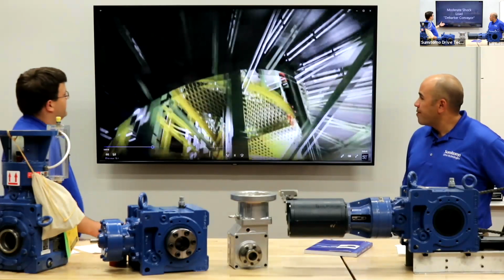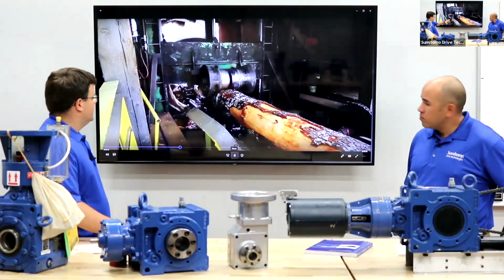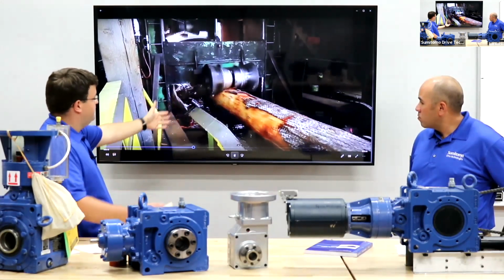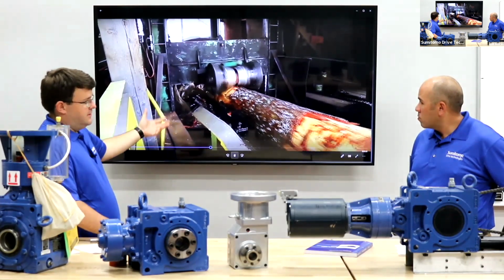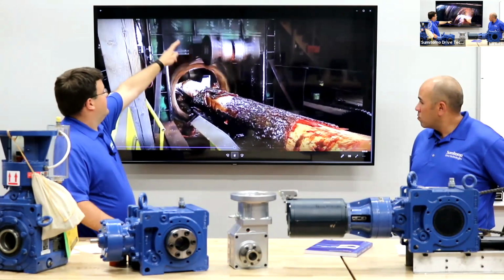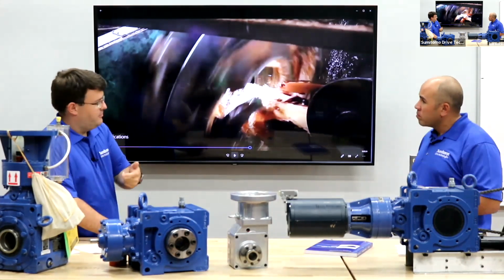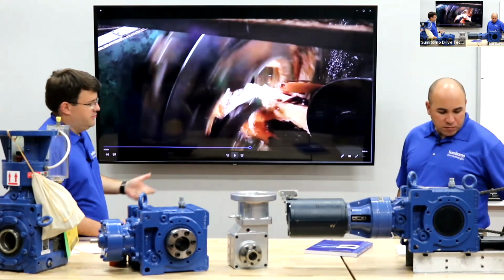And as we move to the next one, the moderate. So debarker, this is in the wood industry. So that's a huge tree. That's probably a foot in diameter. All that weight is on that conveyor. So that gearbox is taking that weight. But then you have that blade spinning that's taking the bark off. You have that roller that's sitting on there. And if there's anything in that wood that blade hits, that shock is going to go back to the gearbox. Yeah. So you have to be prepared for that. So it's the unknowns is what you're really looking at.